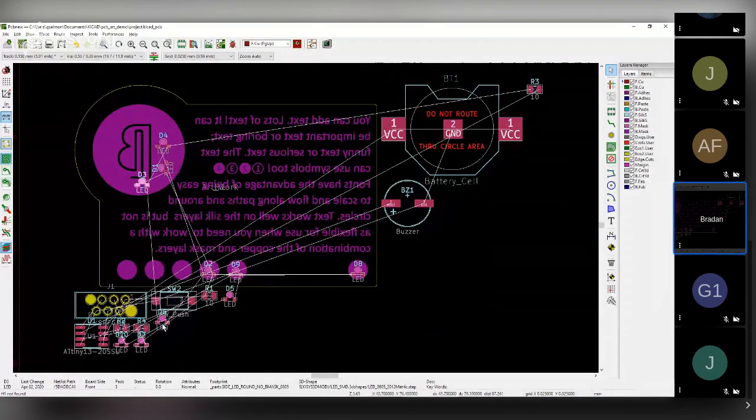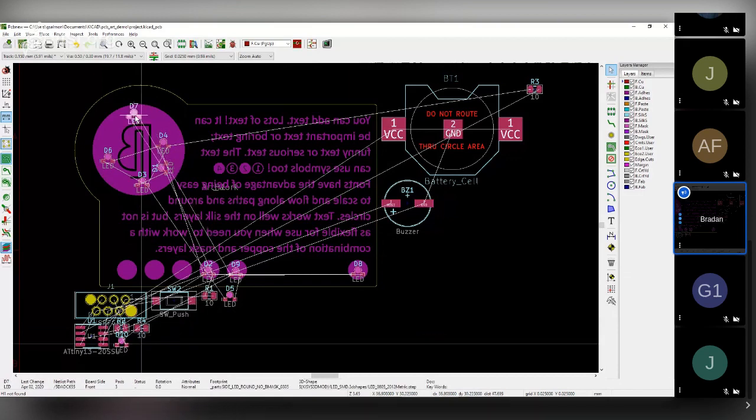What type of LED footprints are you using to shine through the board rather than shine away from it? There you go. You might have seen that picture I showed from the browser. These are what they call right angle LEDs or side light LEDs. They actually lay over on their side, and there isn't a very good footprint for this. I'll show you the two footprints that I've created, and the pros and cons. There's a couple of issues.